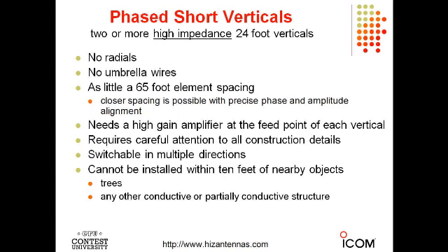But if you have a tall tower close to a quarter wavelength high... on 160 meters, your tower is much shorter than a quarter wavelength. So the re-radiation from that tower is receiving lots of 160 meter signals all the time, and just like any other parasitic element, they get re-radiated.